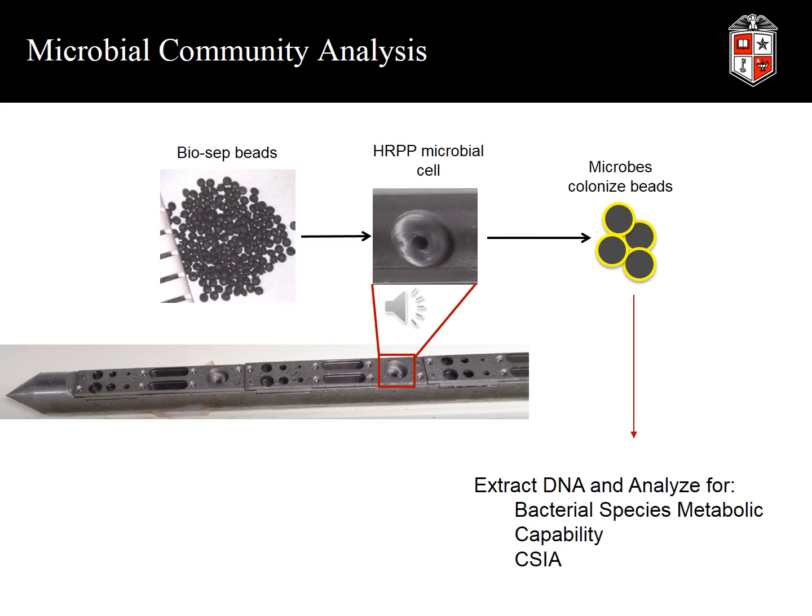So that's a very powerful technique to be able to look at the microbial community and how it varies with depth. In this case, the sampler can evaluate every 20 centimeters. But beyond this, the same technology can also be used to evaluate the activity of that population. To do this, we use a technique called compound-specific isotope analysis, which we will discuss next.